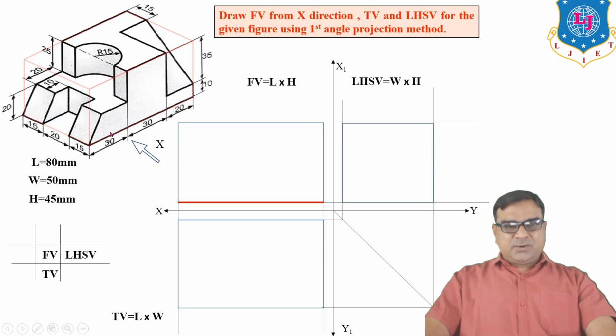Now first you have to draw the bottom plane which is parallel to HP, or base. Because the horizontal plane and bottom plane are both parallel, the front view on the vertical plane is a line. So this is the front view of the base of the object. Now from the right side plane, for this line, vertical, this is a horizontal line parallel to base. So front view like this.